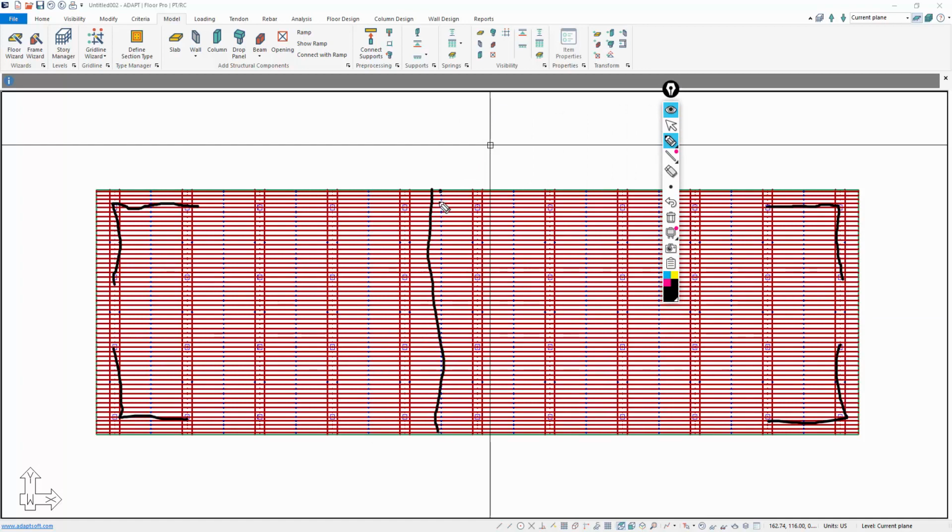Maybe we'll just center it in this span. We'll assume that it's shored during construction until it's closed. You know, we could make the pour strip so that it's offset from either of these frame lines, but we'll just select an arbitrary location in the middle of this bay.